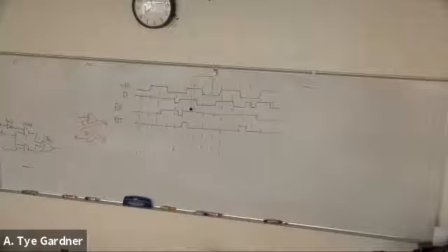Well, let's go ahead and do synchronous because that's looking like more people did, which means that we only care about it when the clock edge hits. So the fact that the enable goes positive, the clock doesn't hit until here. When we hit, the reset is true. So we actually know at this point in time, we're 0.